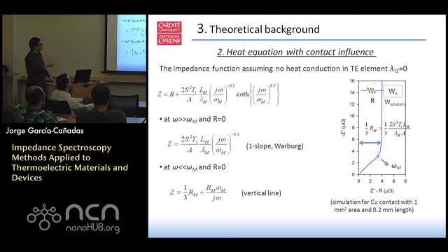So we can fit this response using a resistor in series with an adiabatic Warburg, in this case. And again, we have two regimes: the semi-infinite regime, where heat travels inside the contact and still doesn't sense the boundary. And once it senses the boundary, at frequencies smaller than the characteristic frequency, the real part is fixed, which is 1/3 of Rm. Rm is given by this equation. And then the frequency is inversely proportional.